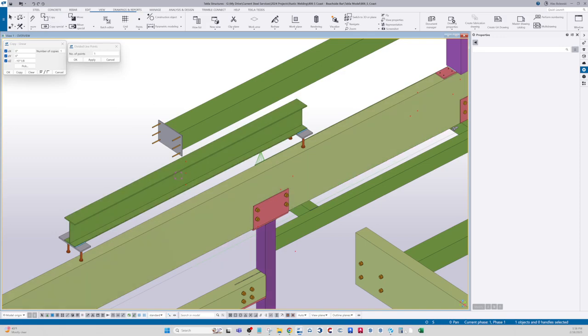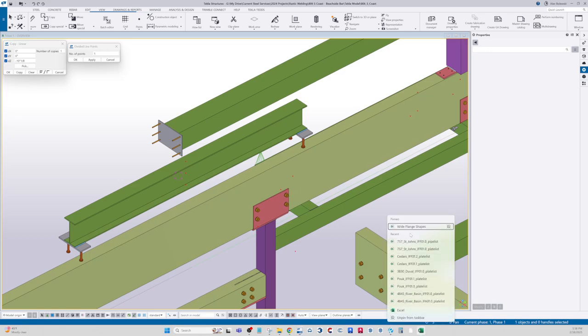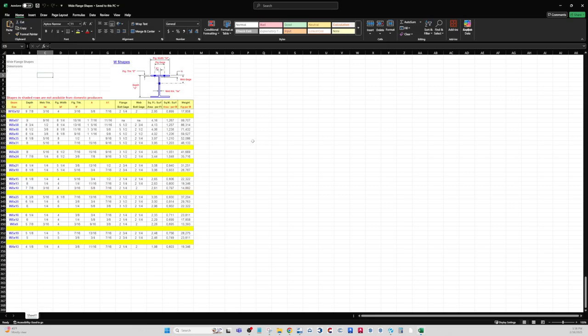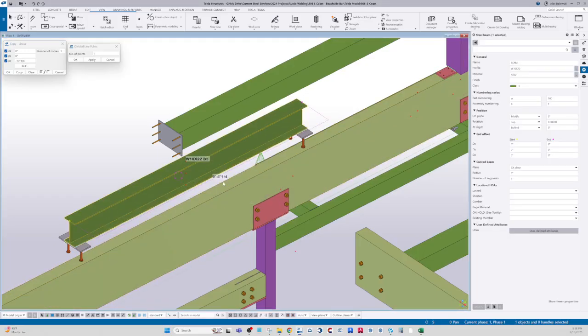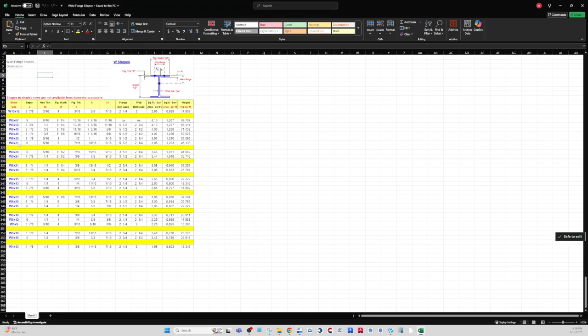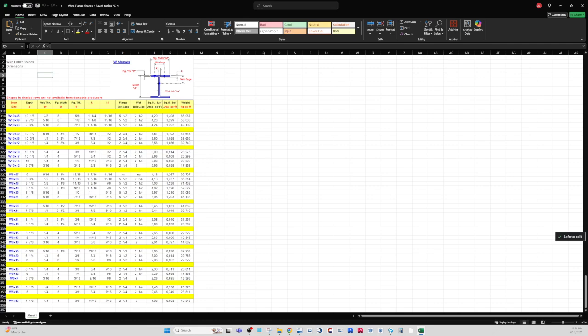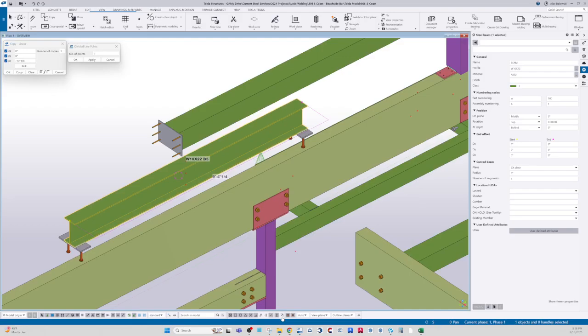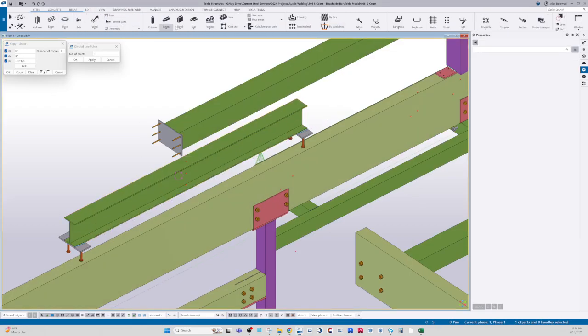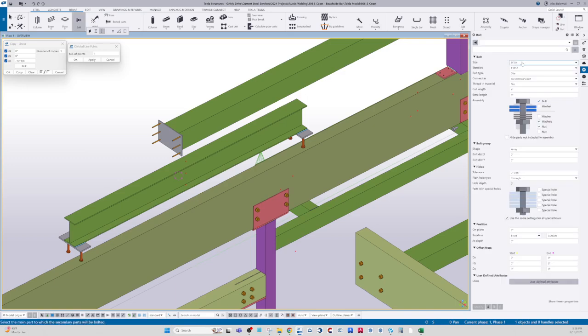Then what you can do is you can look up your gauge line for a W10 by 22. Flange gauge is going to be this. Flange bolt gauge, 10 by 22. Right there, 2 3/4. Oops. So you just come here, bolt. I usually, for whatever reason, just make them A307. A lot of times that's what is in there.